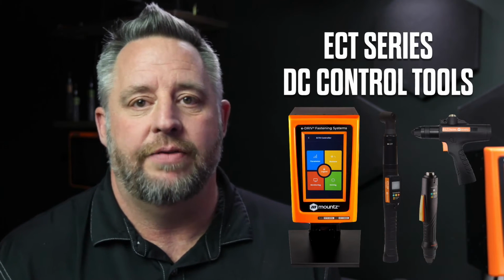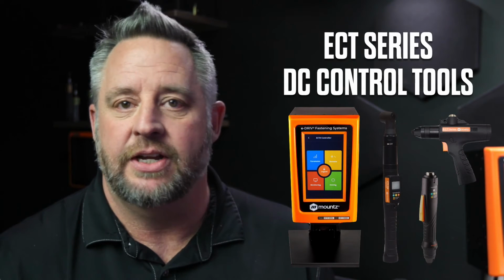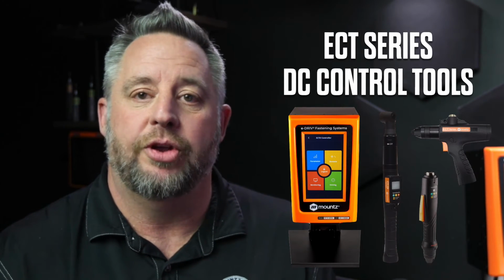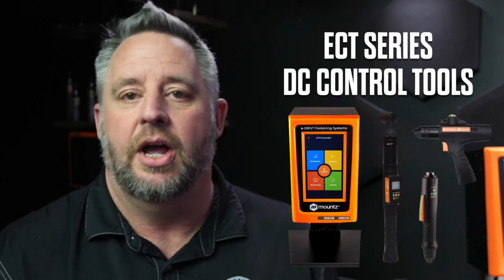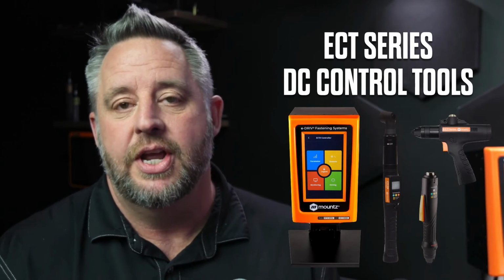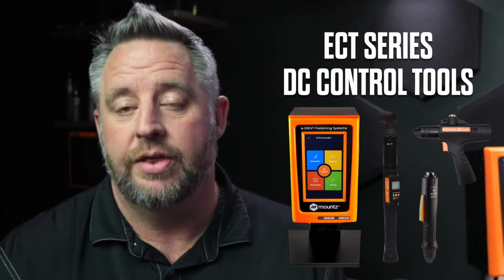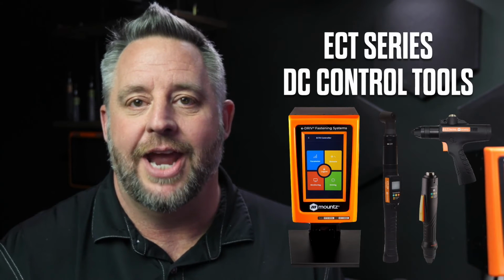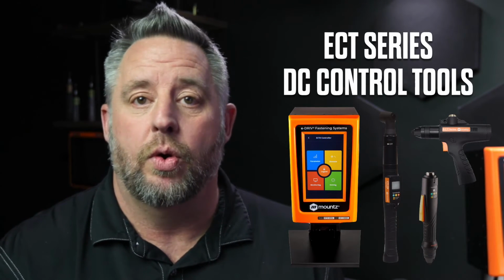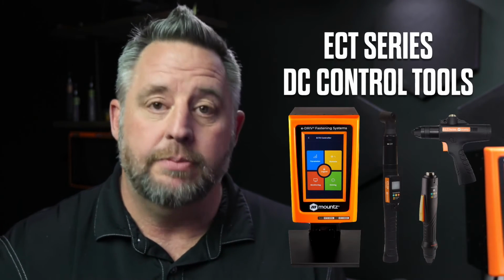These tools do have the ability to have multiple presets, so we can have up to 15 different presets. We can link presets together with our multi-sequence process, and then we also have some of the error-proofing capabilities that we talked about before, along with monitoring the data and the output that happens from any type of torque or error event that we may see with the assembly.